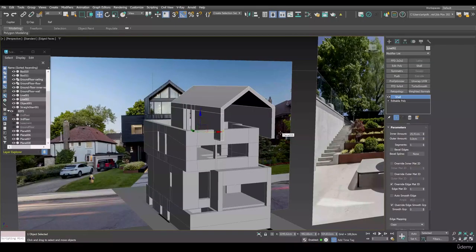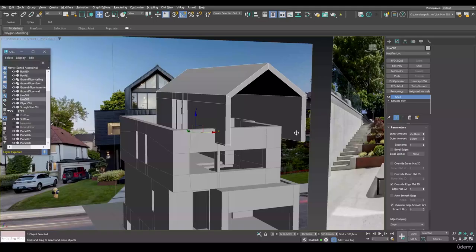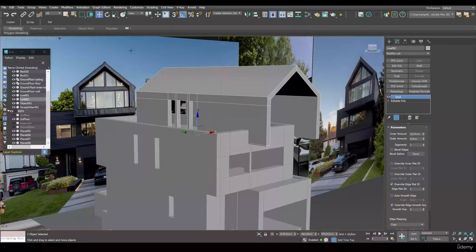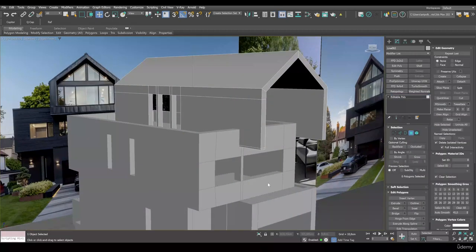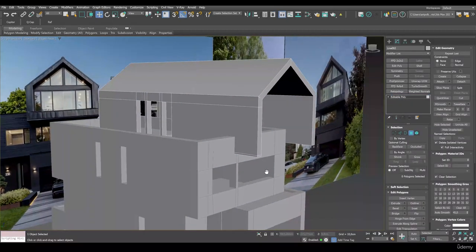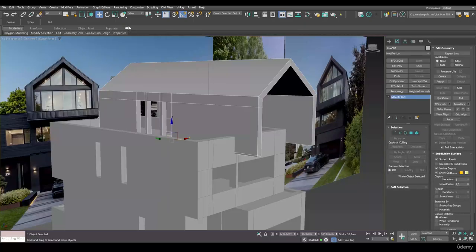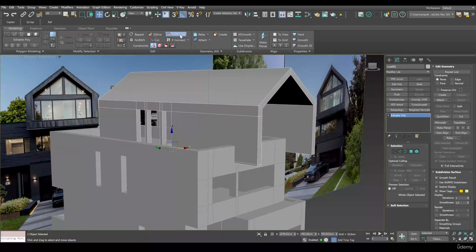Alright, now this part looks correct. The easiest way to add a lintel here is to increase the number of edges and apply the bridge function. Enable the graphite modeling tool. Take the Swift loop tool. Add a loop from the edges at about this height.